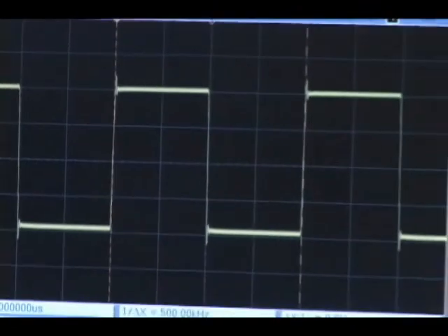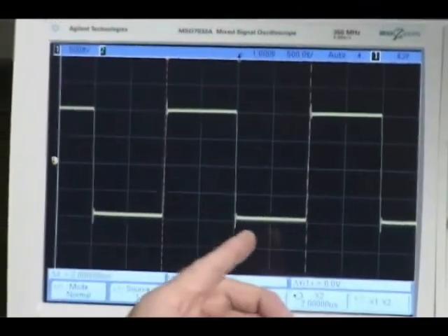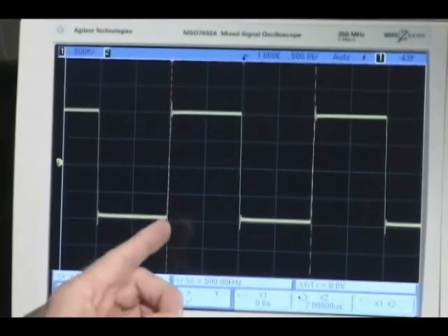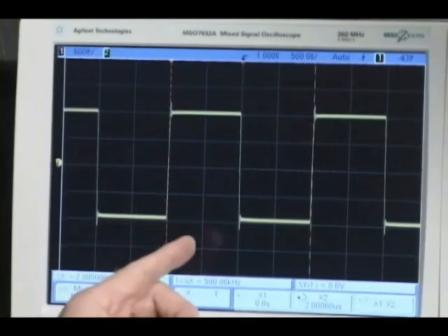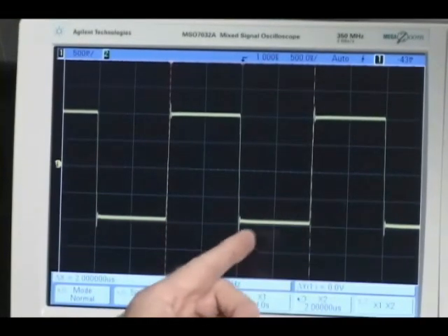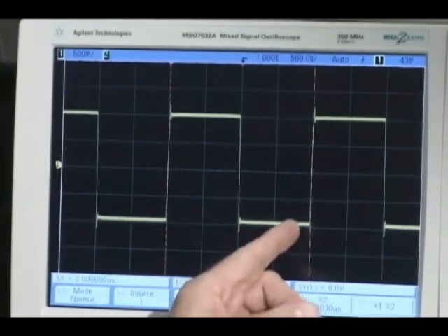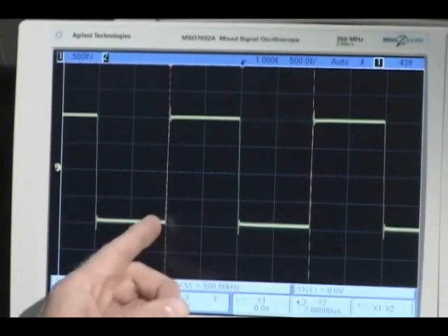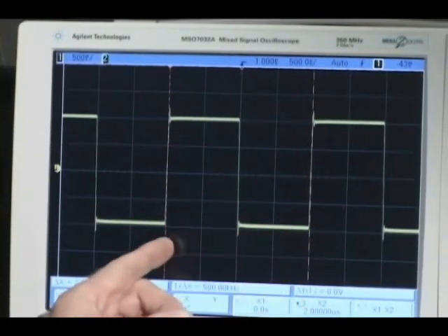Again, if we pan back over to the scope, what we have done by setting the gate hold off is prevent the gate from closing until the conditions of the close, which are the positive edge, have been satisfied, those occurring on the next rising edge, therefore giving us a measurement of the signal period.